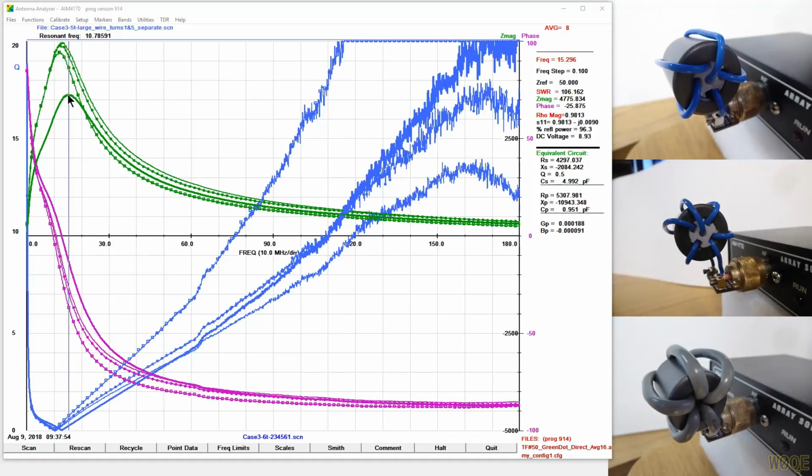Shown also here in a wide graph is the effect of 5 fat turns with larger wire that are put through here, and the 5 turns fill up this area pretty nicely. In this case, the input turn is on the bottom here, and the output turn is up here. I wanted turn 1, turn 2, turn 3, turn 4, and then left the space at the top. It's probably easier to not do that. The effect is really pretty insignificant, which was interesting. I was thinking it would be a little bit more significant than that, but it doesn't appear to be that significant at all.